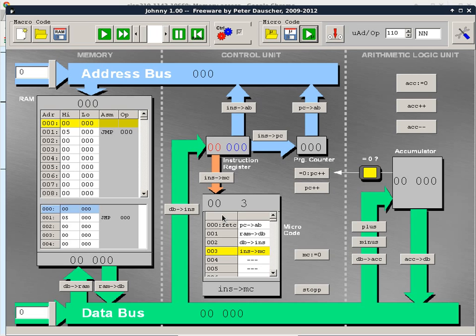So if you have 0 in the fetch, then it's going to stay 0 no matter what, right? If the fetch cycle itself is instruction opcode 0, then it stays 0. Yep. So with the other instructions, this is also something that you can do to find out what the instruction does, but at a microcode level.